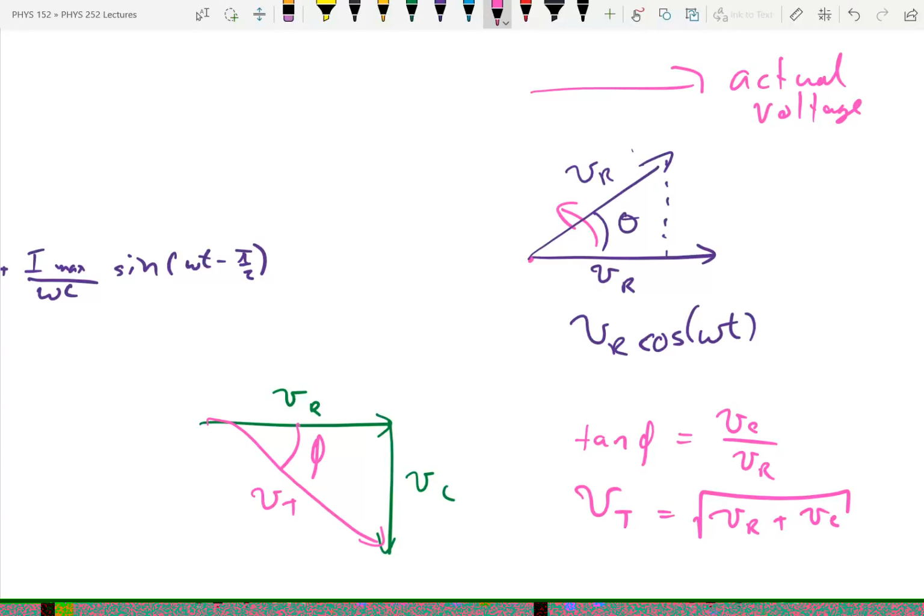And so that's what we're really doing with the phasors. We are graphing, essentially, I mean, that's the basis of it. Graphing the voltage across the resistor, across the capacitor, and saying, okay, only this projection is what the actual voltage is. The other projection is meaningless because the voltage isn't really going around in a circle. But because it's changing sinusoidally, we can use the circle as a mathematical tool. So that's where we get our phasor idea from.